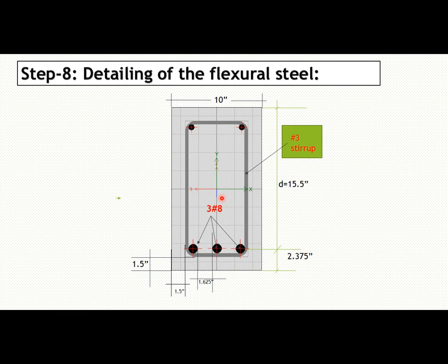You know that we must design a section as an under reinforced section, because in an under reinforced section the failure of the beam occurs when the ultimate flexural capacity is reached by yielding of steel first before crushing of concrete, which ensures the ductility of the section.